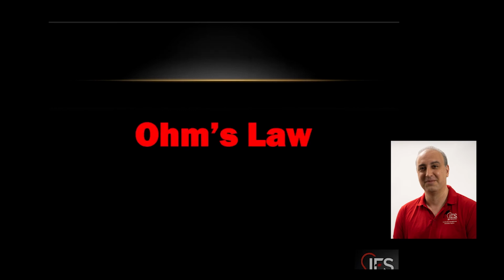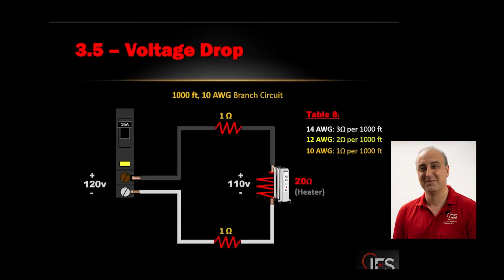Any questions on voltage drop? Everybody's clear? So yeah, go ahead. Okay, that's your voltage drop calculation. You did that, right? So all I'm saying is that that voltage drop calculation tells you that you'll have a 10-volt drop if that's the wire that you have. So a 10-volt drop will get you, instead of 120, you'll see 110 at the end.